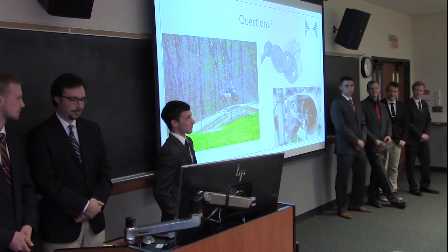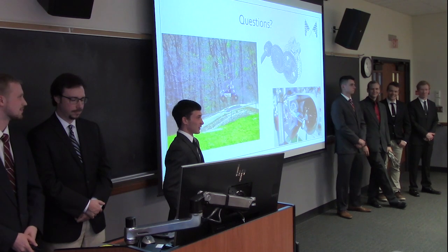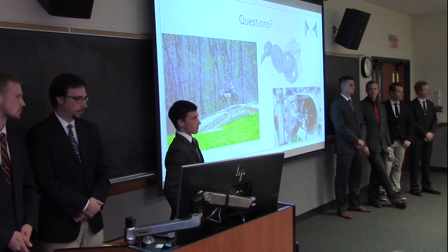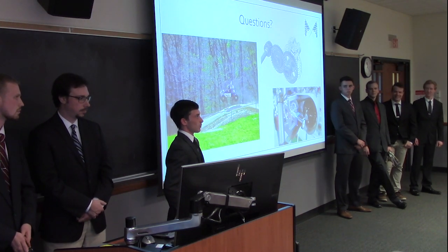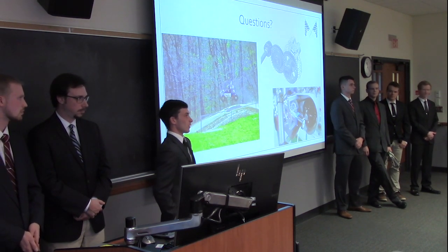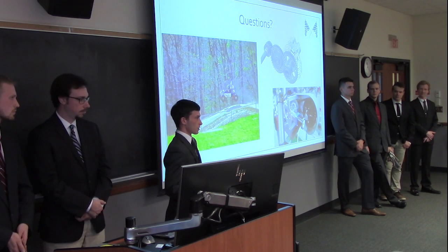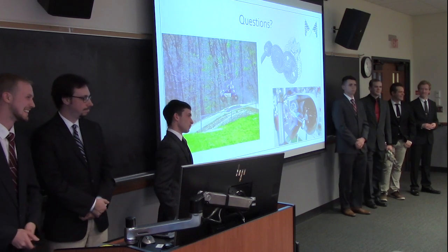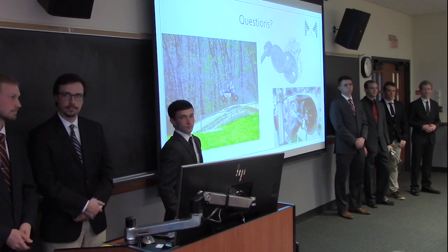Yeah, we did not analyze our keys as well as we should have. We actually broke a key, but we believe the key was made out of a mild steel, and we're looking into high strength steel alloys for that. We created a 3D printed scale model of the transmission, and we tried putting a torque into our 3D model to see where the gears would fail, because we didn't have budget to break actual components. But if we could have made multiple transmissions and test them to failure, we would have done that. Okay, thank you, folks.